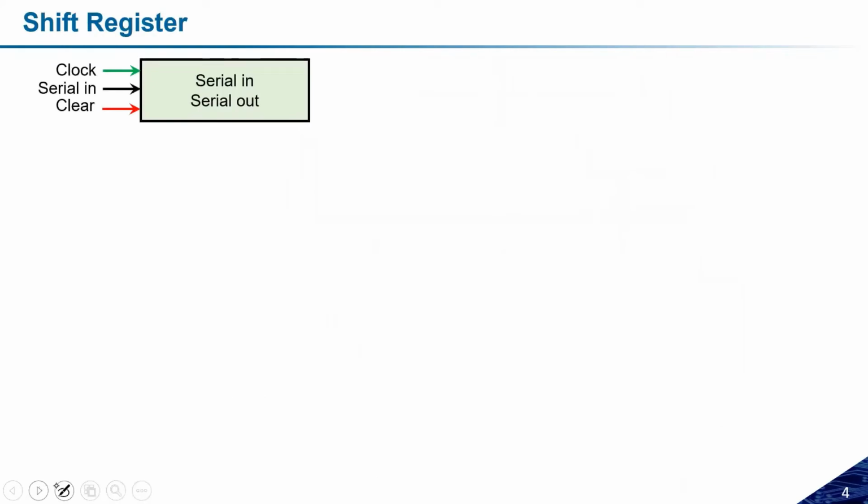So that was the example. Let us now consider the serial input, serial output. In the serial input, serial output kind of structure, I can provide input to only one flip-flop, either on the left or right, and I have to take the output from only one flip-flop. So what does it mean? What is the complexity? I will tell you, because I have to perform only one bit at one clock pulse.